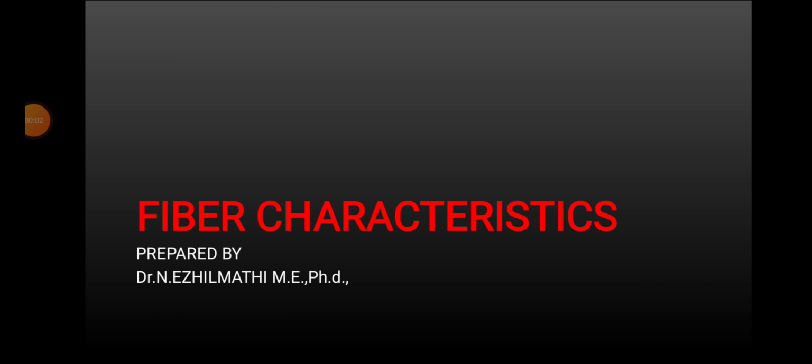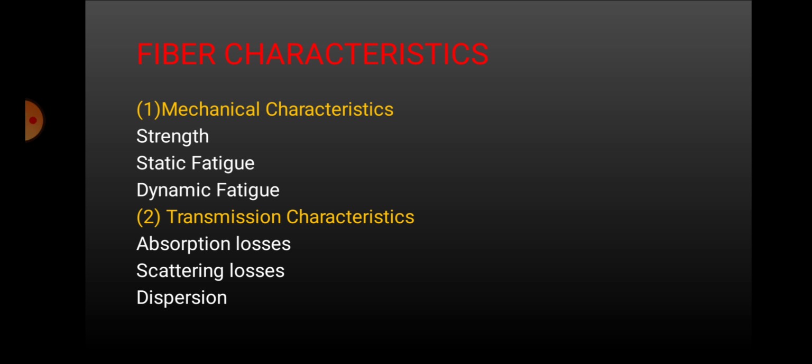Good morning, students. Today we are going to see the topic fiber characteristics. Two important characteristics of optical fibers are mechanical characteristics and transmission characteristics. The important mechanical characteristics of optical fibers are strength, static fatigue, and dynamic fatigue. And the transmission characteristics are absorption losses, scattering losses, and dispersion.